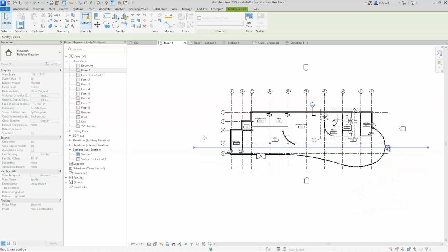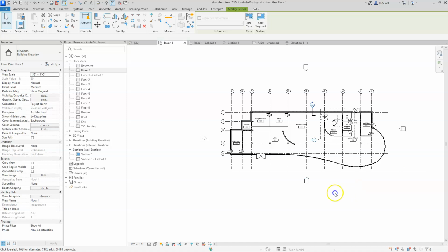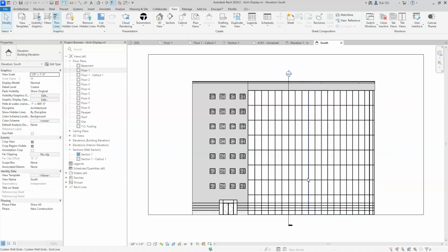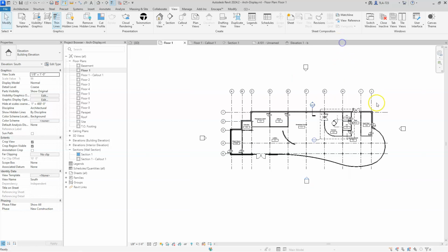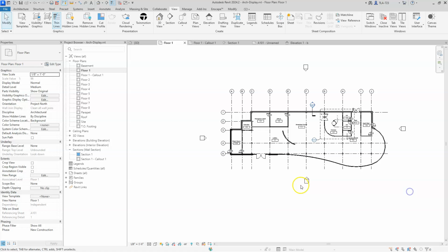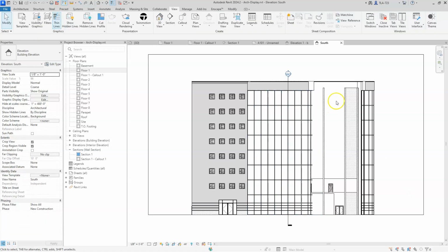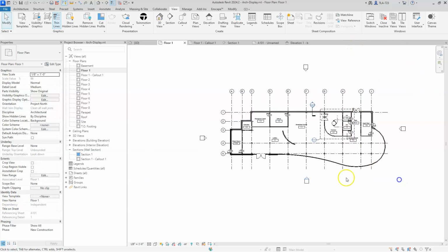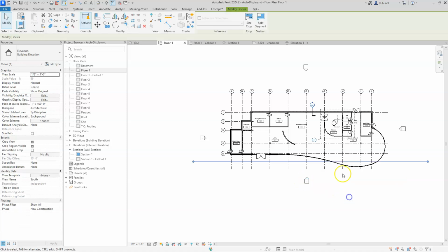Similarly, if it's too far forward, we're actually going to be cutting into that building. So let's go ahead and see what that looks like. If I drag it right here, I'm outside the building, and I open that view, you can see that I can see the entire exterior of that building as intended. But again, I'm selecting the triangle part, if I drag that thing into the building a little bit, look what that does to the view, how it changes it. You can see I'm now cutting through that portion of the building. So we just need to understand what that line is and how it works so that we can make sure that it's placed correctly.